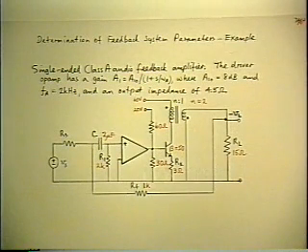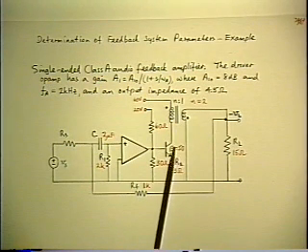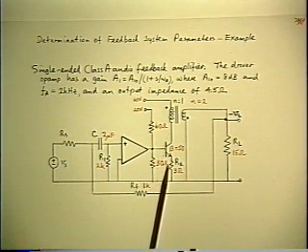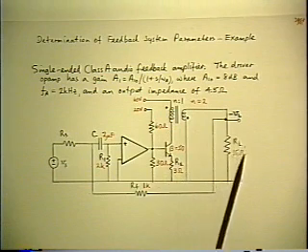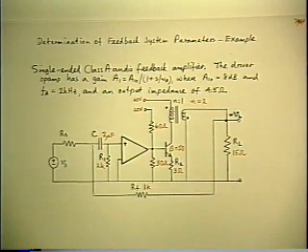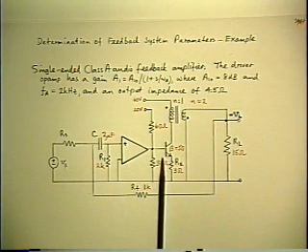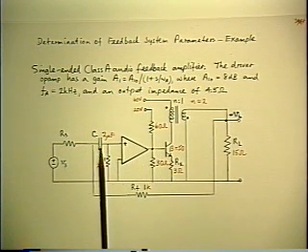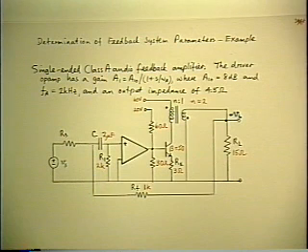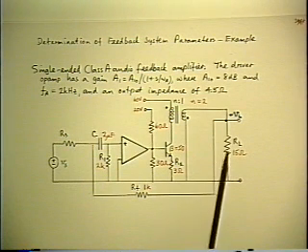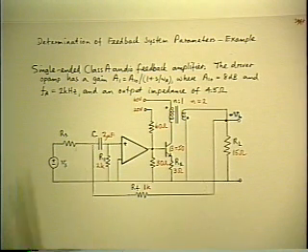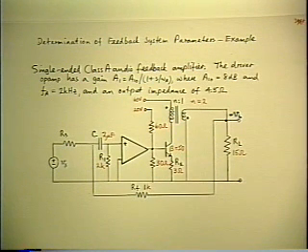A very primitive little audio amplifier. Single-ended Class A power output stage, transformer coupled to a 15 ohm load. There's a driver stage and an interstage network at the beginning, and feedback is taken from the output back to the input.